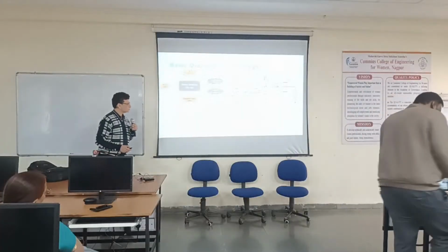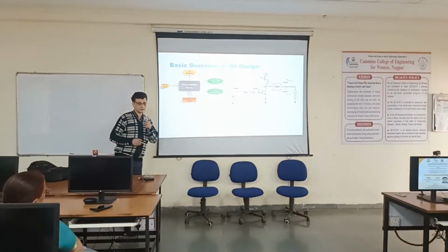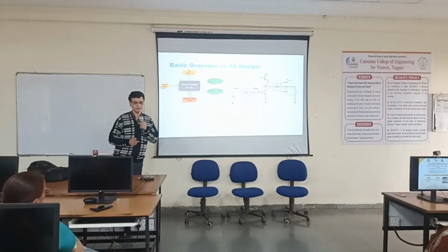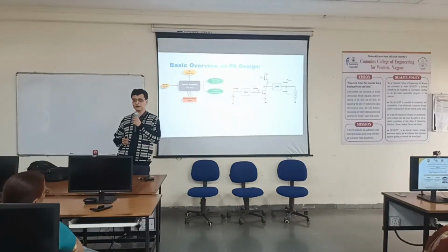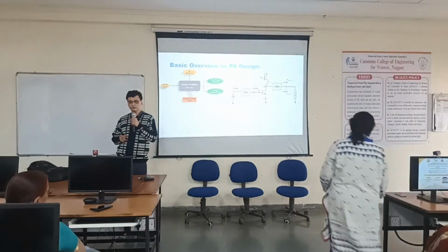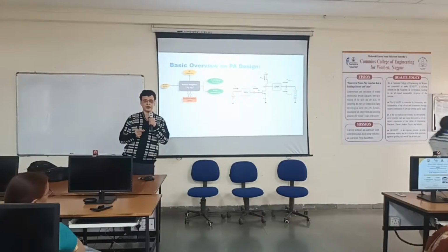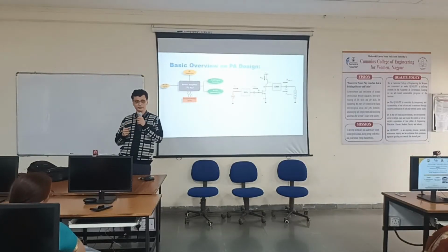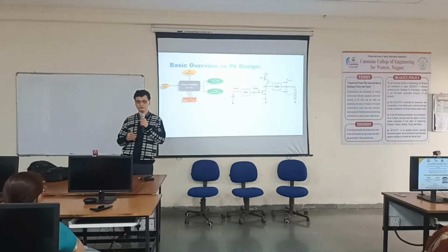Okay, so this is the schematic of a power amplifier. Power amplifiers are used in many places, especially for 5G. They become very important because for the 5G standard, there is a special modulation scheme called OFDM, where you have very narrow bands, and the amplifier has to provide amplification both at peak power as well as what we call back off power, somewhere between zero and the peak.